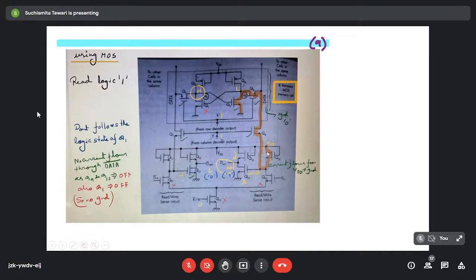So it is getting a clear-cut path from this VDD to this ground. As soon as the potential of this particular node is pulled down to 0, it is basically switching off this Q14. Now the gate terminal is getting almost a ground potential, if not exactly ground potential, that falls under the logic low level. Suppose it is now getting 0.1 volt or maybe 0.01 volt, but that 0.01 volt is basically considered as logic level 0. So now this transistor is switched off.